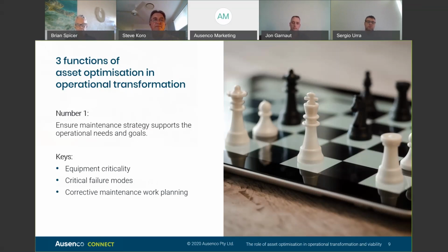Another criterion is safety. Did this affect safety? Absolutely. Another factor is costs. Absolutely. This mine was shut down. The inspectors were there straight after the event. Huge costs. Did it affect the environment? Yes. Did it affect health? It could have done. So this is why criticality analysis is really important to fully understand, because overlooking things like an ammonia plant away from the main production can cost you dearly.